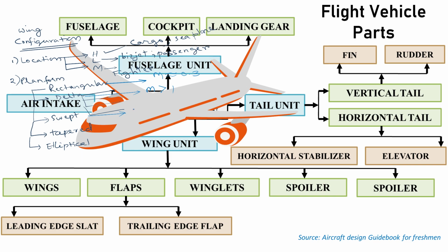Transonic. Very good. So when we are in the transonic range, the swept back wing starts with 0.6 to 0.9, within that range, or sometimes close to 1 even. If the aircraft speed is within this range, it is recommended to use a swept wing. Then taper. Talking about swept wing, mostly we use it for passenger aircraft.